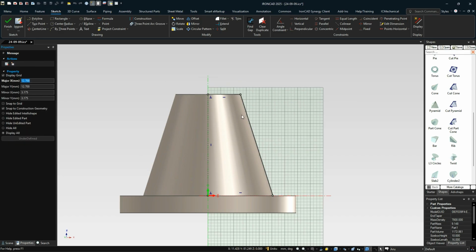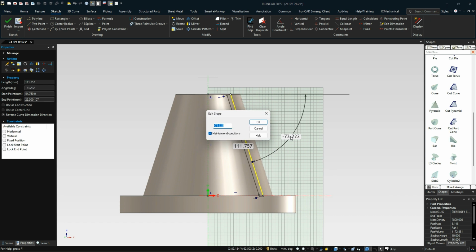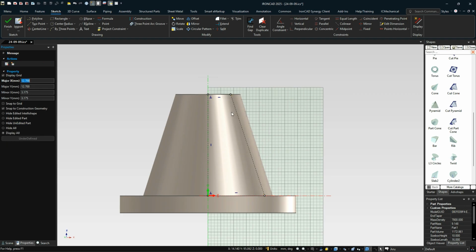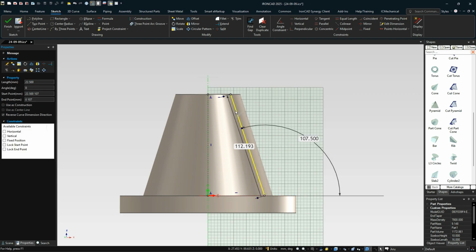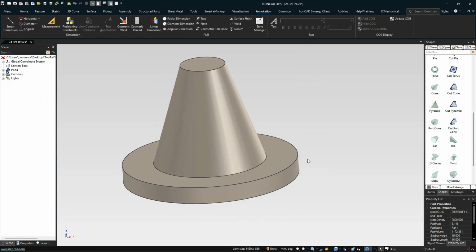A couple of things we want here: first, this length needs to have a value of, let's see, 45 divided by 2, that's 22.5. That will give us that distance and maintain this angle. But in our case, this angle needs to be negative 72.5, and the reason is that it will give us the total of 35 degrees for the angle inside there. So now we know that's our 22.5, and that's the 72.5 if we select on this, to give us our overall angle for that shape. Let's hit finish, and that gives us our starting point.